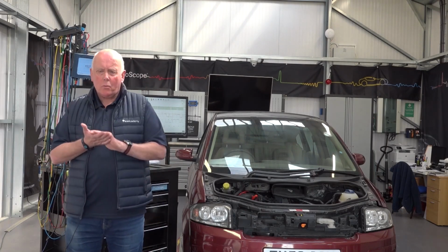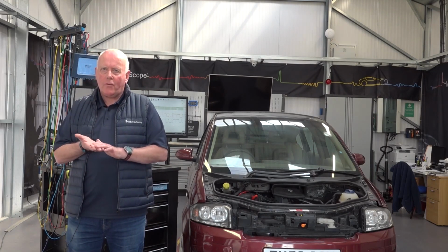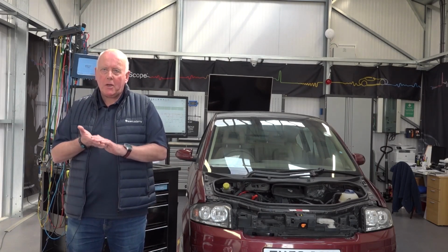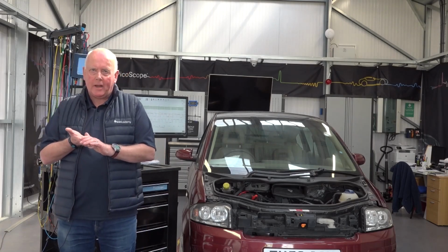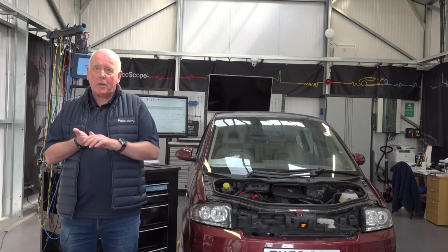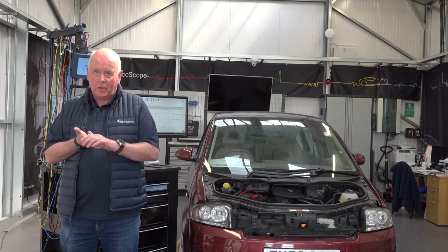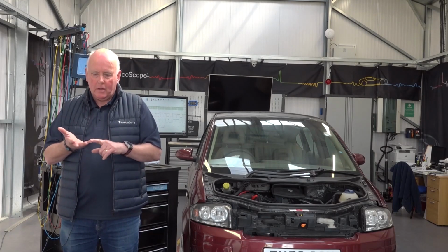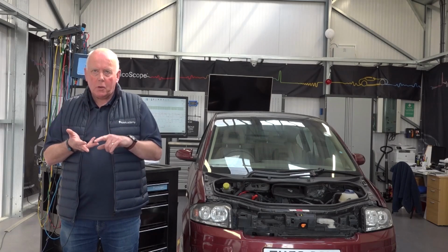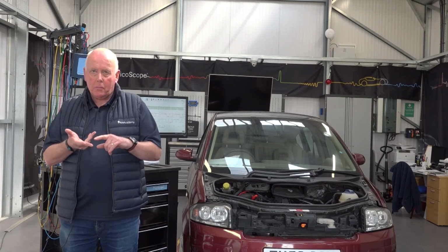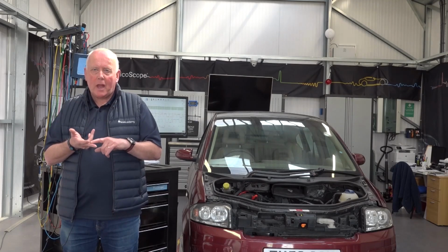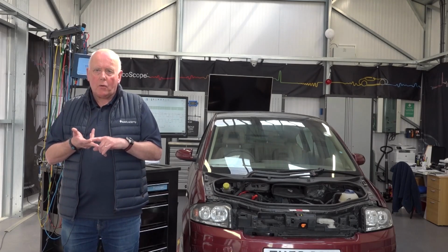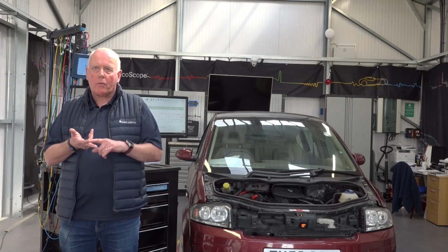Key features, one is always save your waveform, put as much information on the waveform as you possibly can, because in 12 months time when you go back to that you're going to forget totally what you did. Also, not only can you put the sensor type, but you can also put terminal connections, and you can put that in the notes section, and the colour of the wires, so that if you do that particular make a lot, you've got all that information built into your waveform.